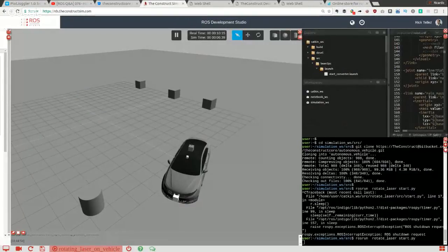Steve Duncan says, Mr. Tellez, I have a question. How can we do this on a real toy car, not a simulator? So how do we add moving TF to the car, to the URDF model? Thank you. Okay, so in a real one, you need to have your joint state publisher and the robot state publisher. Those are the ones that publish the TF. Well, actually, it's the robot state publisher that publishes the TF based on the values that the joint state publisher is publishing.